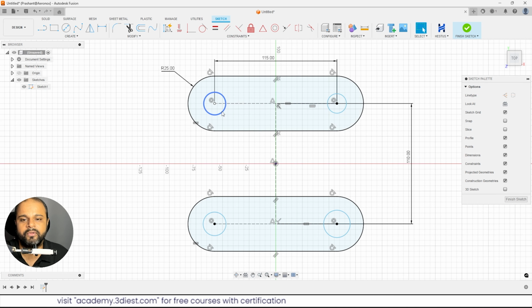Now let's come to the radius: the internal one is 32.5 and the outer is 45. So we go back to our design. We'll dimension this one as 32.5 and the outer one as 45, like this. But here we did something wrong. You can notice these are the diameter values we have defined, but in the design these are the radius values we have to define. So maybe we have to double or decrease these values.